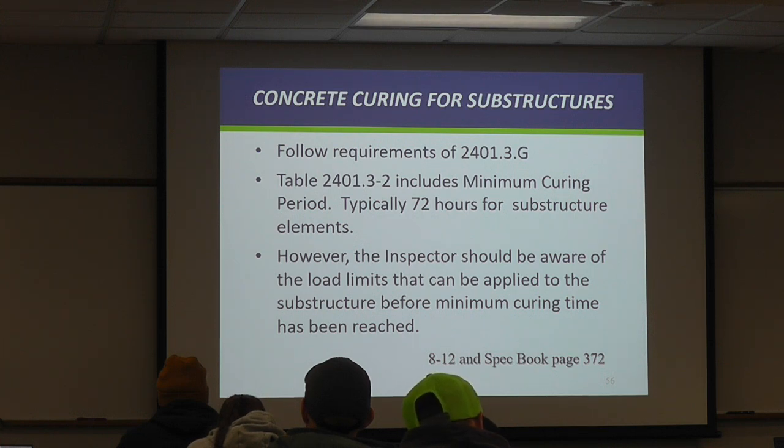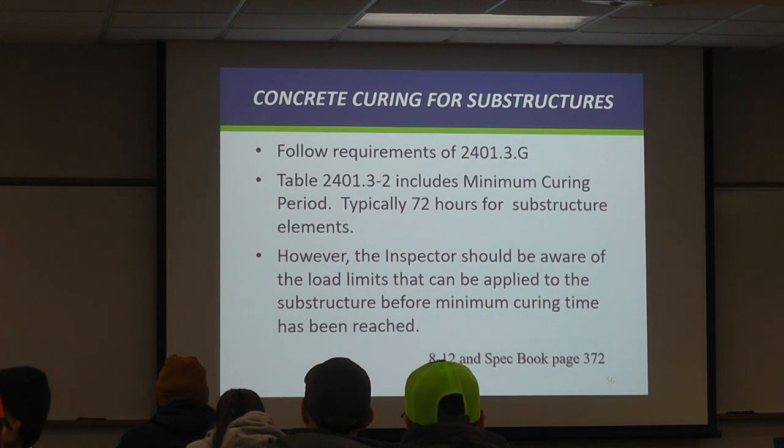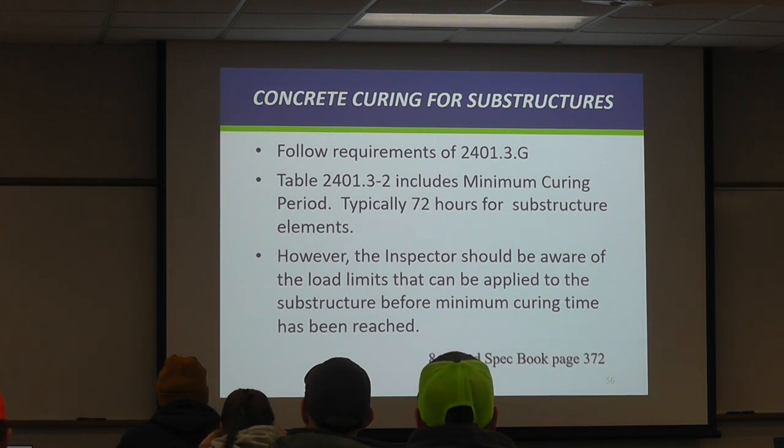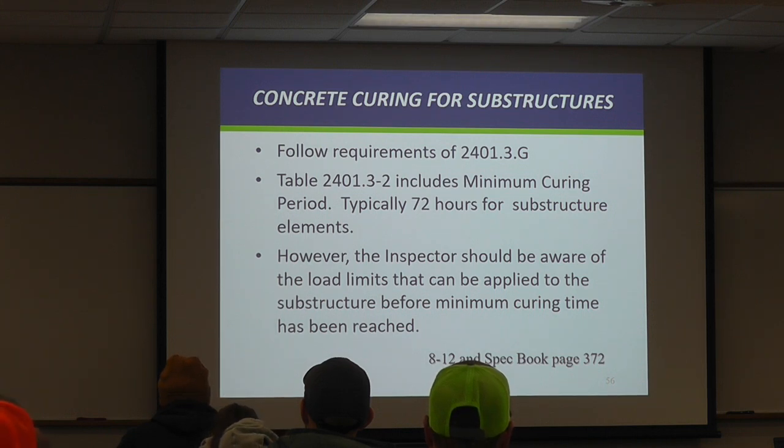Okay, so let's look to the third to the bottom line, the sections not included in superstructures. Unless otherwise specified, it says minimum curing period is 72 hours, and then we go over minimum strength to pull forms. It's 2,000, with a not-equal-to sign. And down in the bottom it says engineer will require verification of the minimum strength when air temps drop below 40.